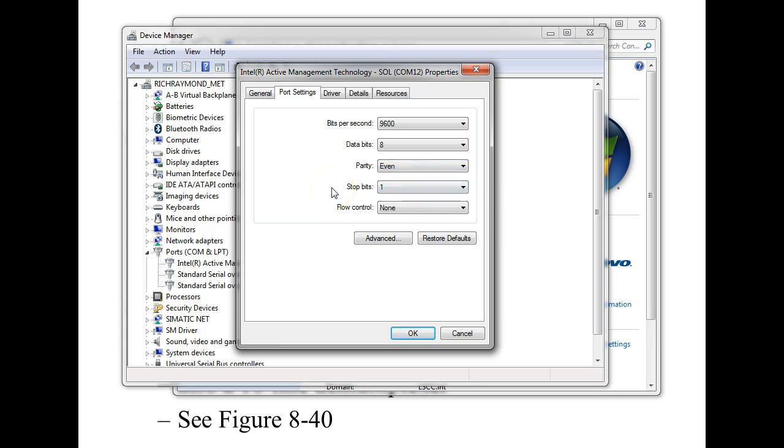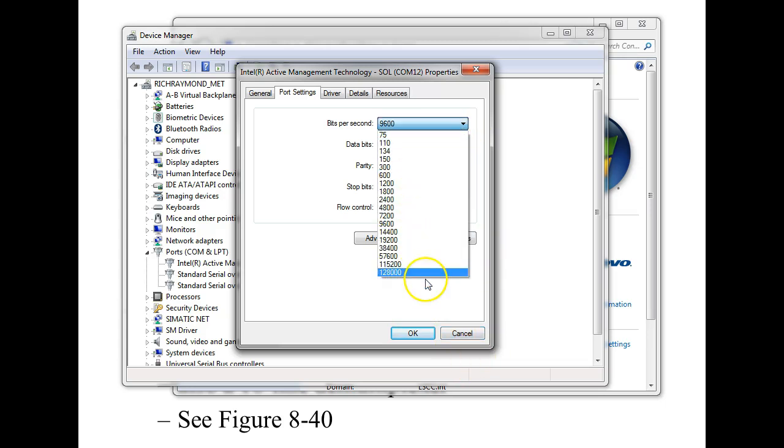So right now, this guy is set up to generate and check what? Even parity. This was a bi-directional port, by the way. But what happens is we don't see this anymore. Why? Because of plug and play. Everything's plug and play. So this COM port was set up for me. So something in here thinks it's a COM port, even though I don't have the COM ports out here anymore. This is where we set the bit speed. So the fastest we could go on the COM ports was 128 kilobits per second. That's slow, right?